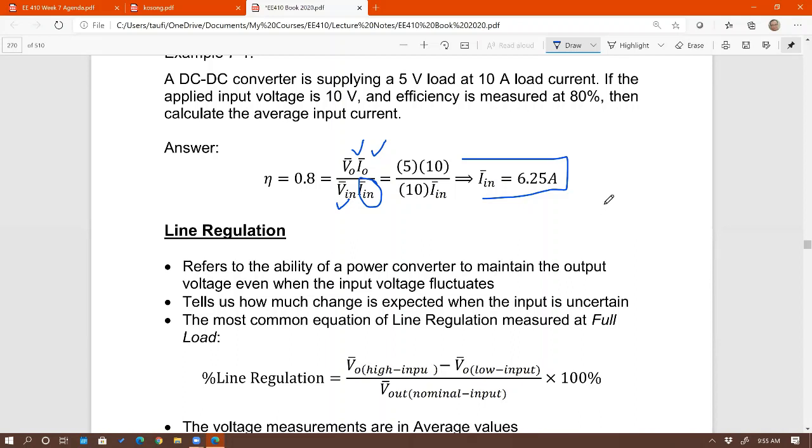So from there, we know that since the maximum output power is 100 watts, and output voltage is 5 volts, therefore output current at 100% load or full load is 100 divided by 5, 20 amps. Okay, so that's what determines the maximum or full load current. Based on that value, you would select components, based on what we're going to cover in this chapter. There are some equations for you to select the proper MOSFET, proper diode per given current. Does that answer your question?